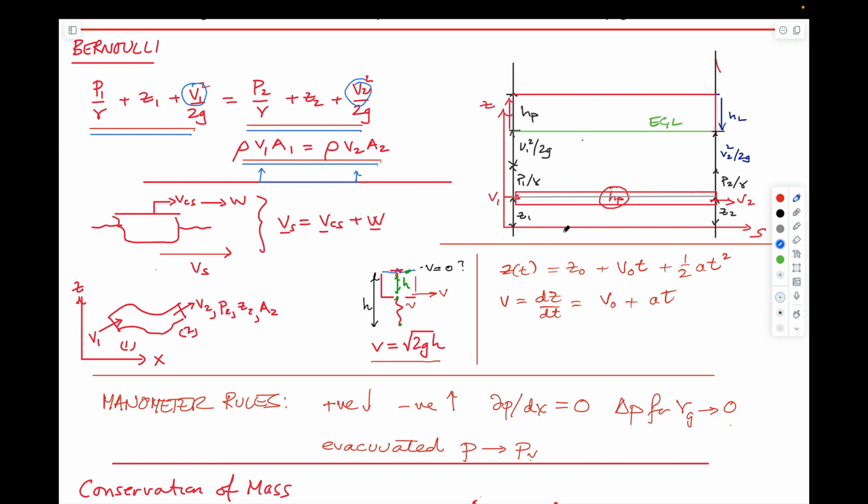We talked about Bernoulli defined in terms of a graphical description. So far we haven't talked about pump heads or head losses, so everything is limited by a horizontal energy grade line. And so we can think about flow along a pipe, if you like, from an upstream elevation to a downstream elevation.